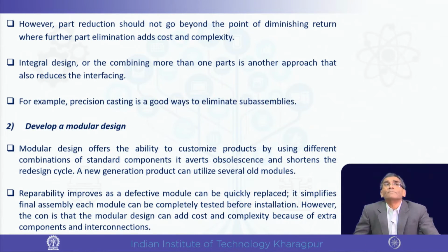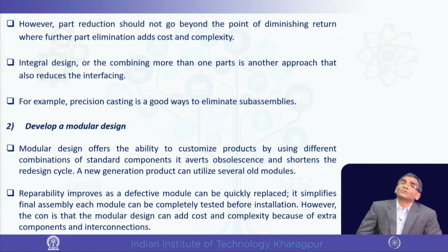However, one thing I would like to tell you is that while part count is to be reduced, there will be some point beyond which if we try to reduce it, the cost may not lessen, it will go up, as it will become a completely integrated heavy part. This is based on integral design, which has certain disadvantages. In the product architecture lecture, we have already discussed modular design versus integral design.